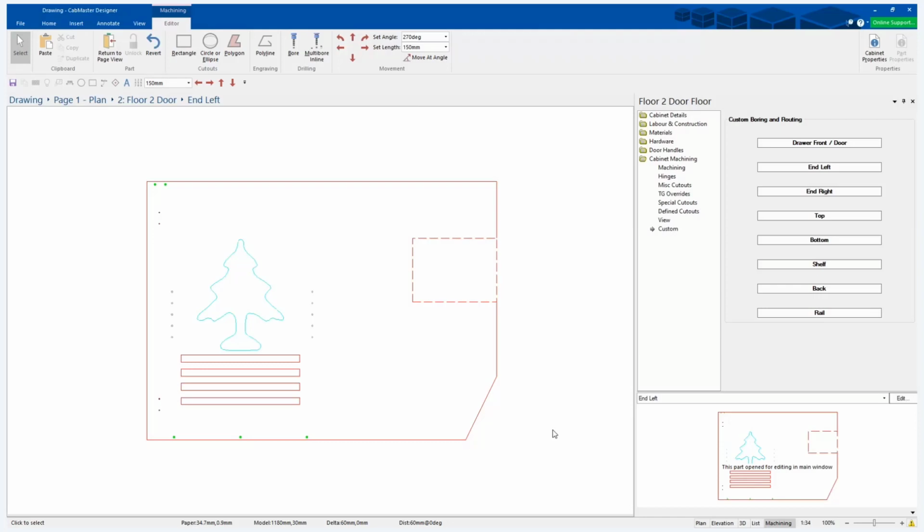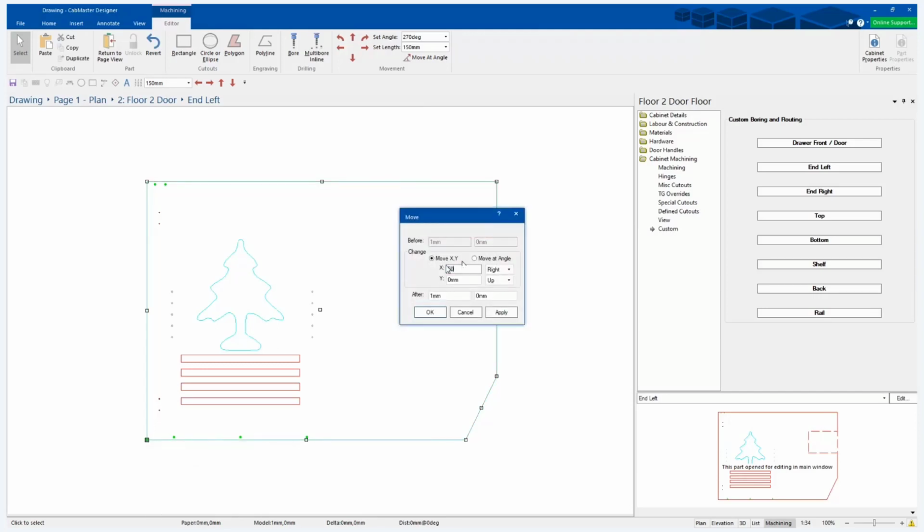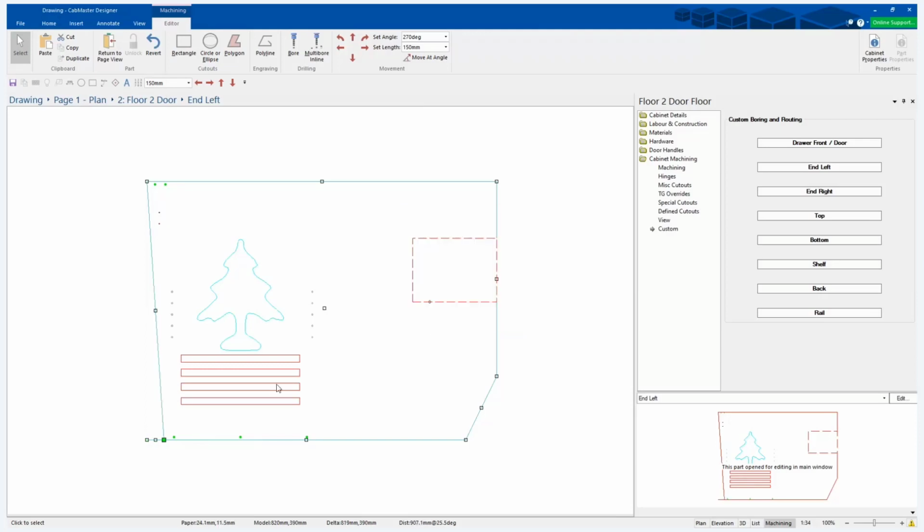So again, different ways to do things. It's thinking outside the box. And again, you could quite happily specify the length of that section and the length from that corner. So come in here, come in a certain length, or I can actually move the corner 50 mil to the right, and that will move that corner there. I'll delete that over there, remove corner. And you can add another corner here and do it the right size. So the answer is yes, there's different ways to do things. A chamfer by definition is 45, but you can do a different move to get the same result, if that makes sense, if you're doing it not 45 degrees.